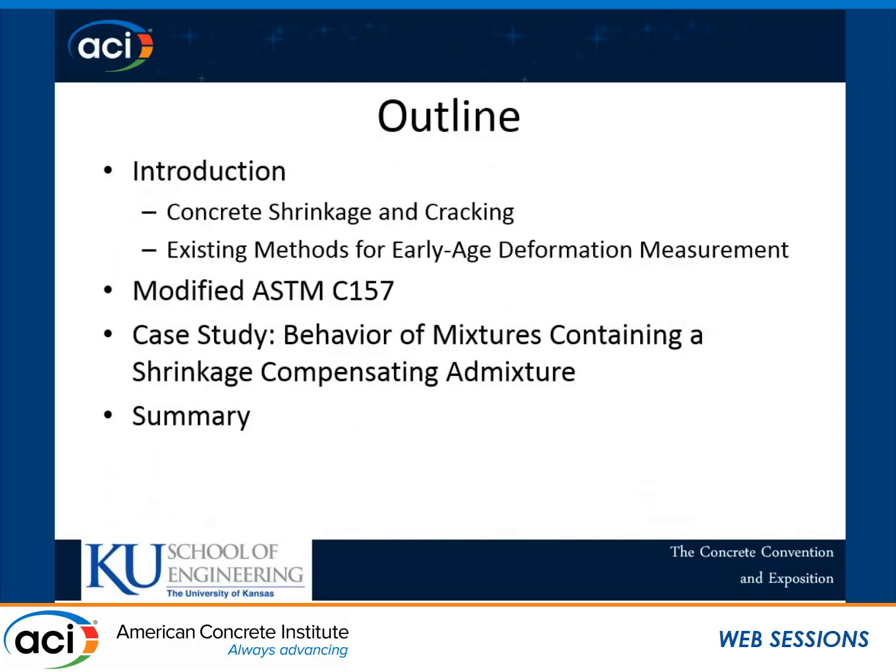The presentation will start with an introduction, in which I will briefly talk about concrete shrinkage and cracking. Following that, I will talk about the existing methods that aim to capture the early age deformation of concrete specimens. After that, I will talk about ASTM C157 and our modifications, followed by some case studies featuring the behavior of concrete mixtures containing shrinkage-compensating admixtures. And finally, I will wrap up with a summary.